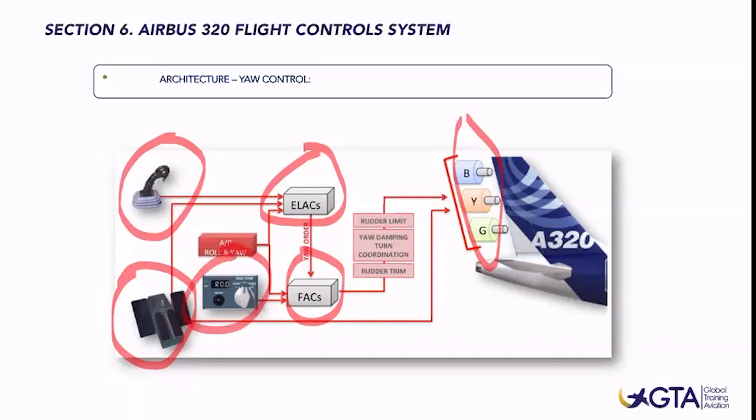Well, additionally, we have the rudder trim, which is an electrical knob. Remember that we have the possibility to trim our rudder position as soon as we are flying in manual mode with autopilot disconnected. Especially, we use this rudder trim when we are performing the engine failure during takeoff after V1 scenario profile, since we are getting some asymmetry in the thrust power. We are still flying with autopilot off, and we need to center and remove this yaw moment. Well, we will need to use this rudder trim knob.